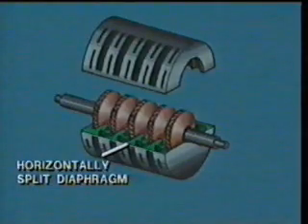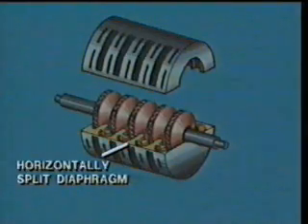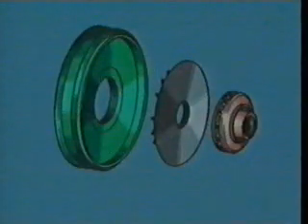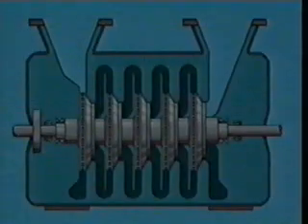In large horizontally split compressors, the heat from gas compression can cause the case to expand, which in turn expands the diaphragms. If this happens, lower gas pressure and leaks could result. Sometimes this problem is corrected by circulating cooling water through the channel. In stacked casing designs, the diaphragms are one piece and therefore provide greater stability and strength. In addition, the one-piece design eliminates interstage leaks and helps contribute to higher efficiency.